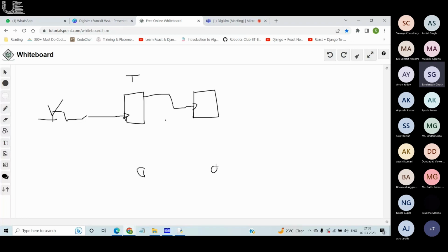So every time I click on the button, this flip flop will toggle, going between 0 and 1, right? Say the first time I click, this becomes 1. Let all of the flip flops be positive edge triggered. So when this output goes from 0 to 1, this gets triggered.